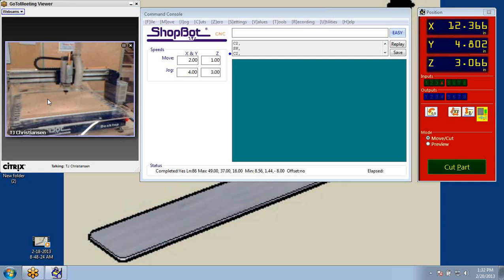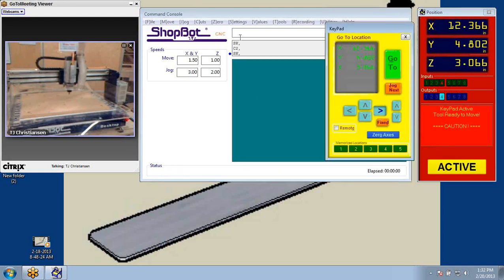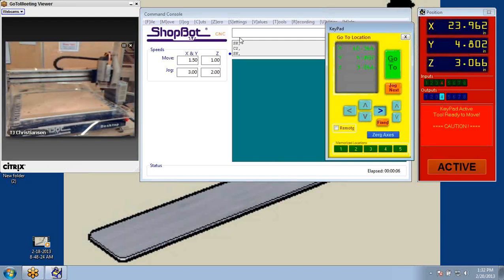So let me show you an example of crashing the machine. Let me just bring the keypad up. We'll get into moves here in a little bit. If I crash my machine where I move this over here, and it starts doing that, I've obviously crashed my machine. Now watch when I push a little bit further how this X can't move anywhere physically, but look at the numbers moving. They're still moving on the machine. It's thinking that it's going.